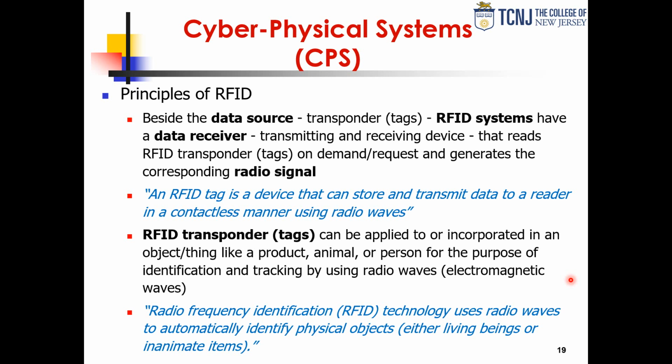Another thing that you have in this label as part of the metallization is a capacitor, so that you can actually harvest energy from the same reader that is trying to query you, and then charge up that capacitor first, and then use that energy that you harvested from the same RF frequency that you're going to be using to communicate to do the rest of the transaction. Okay? Receive the command and then send your ID. So that's sort of the way it works at a high level.